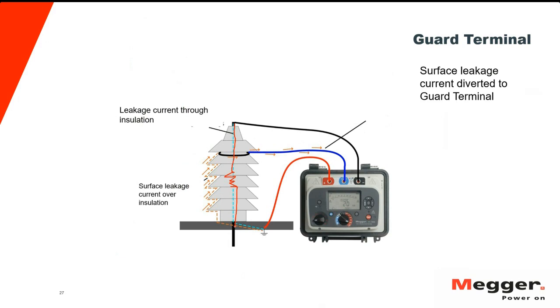But remember here, if you do the trending analysis, you need to make sure that if in previous years or previous tests you did not put a guard, and then you put the guard here, you might wonder, oh, why did my resistance get improved? Most probably because in the previous test the guard was not used.